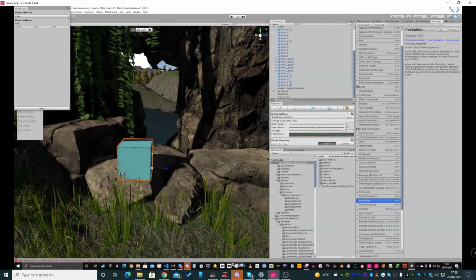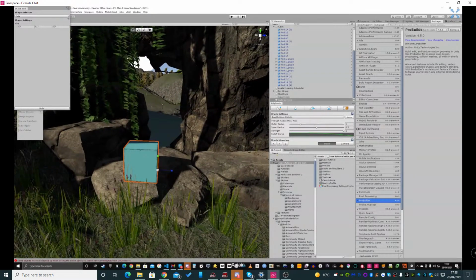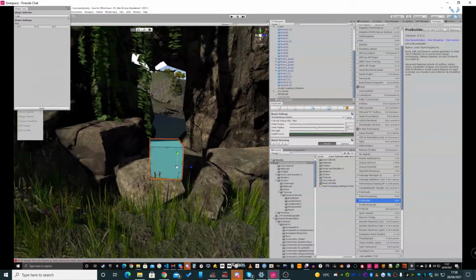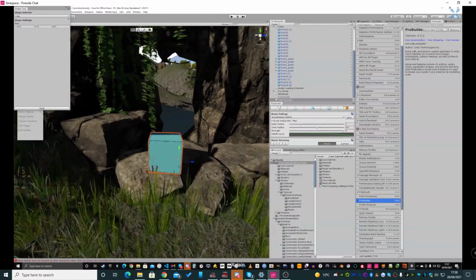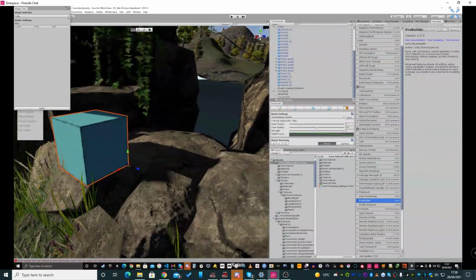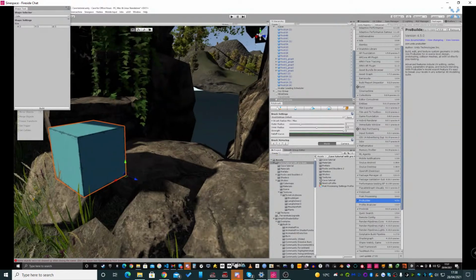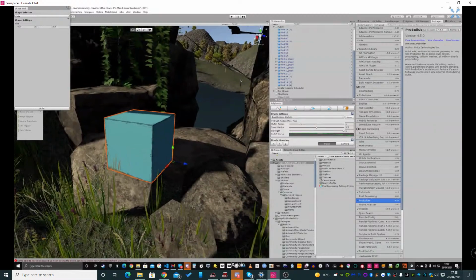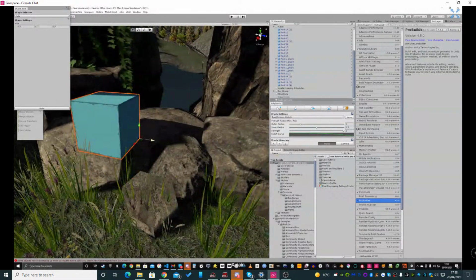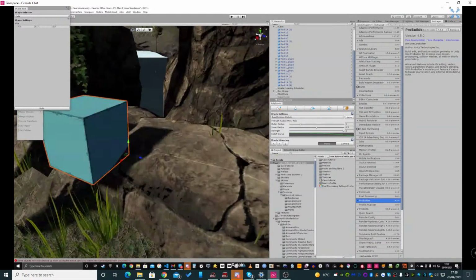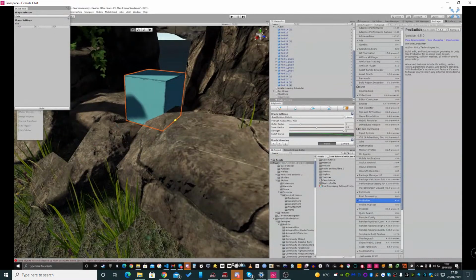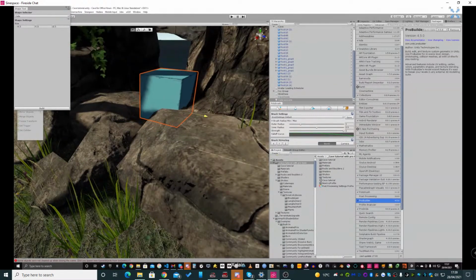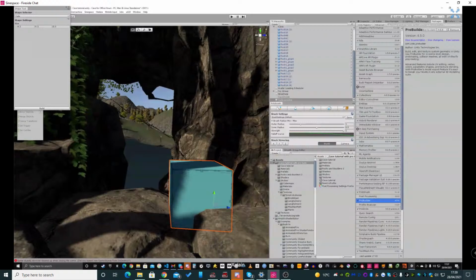So, the other thing with ProBuilder I forgot to mention is it always puts its pivot point down in one corner, which is kind of quite handy. It's handy for ProGrids because you're always snapping to the edge of one of the snap points, and it's handy for scaling because I can move this over here to the side of my hole and then scale up. And instead of scaling all sides and me having to move this cube again afterwards, I won't have to.